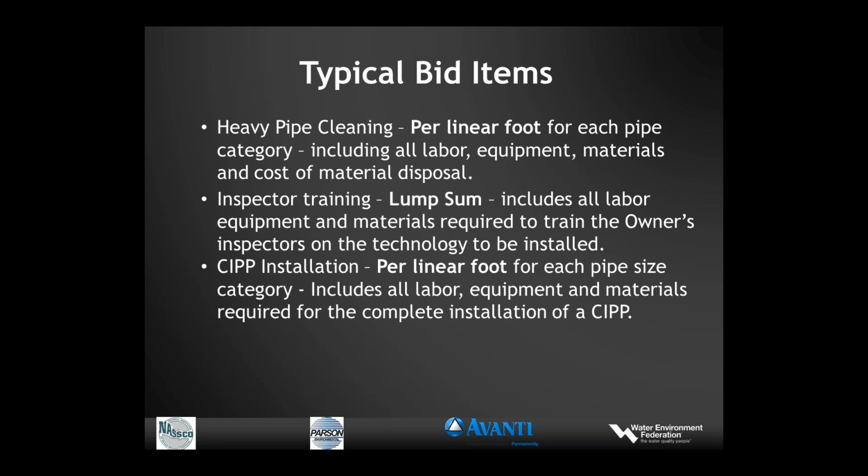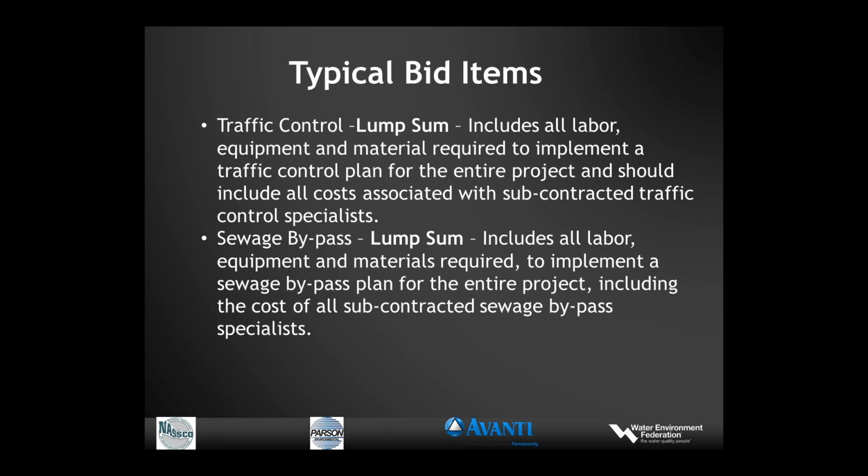Pipe cleaning and heavy pipe cleaning, inspector training. May want to include a bid item to train the inspectors for the CIPP inspection on this project. NASSCO does offer the inspectors training certification program. CIPP installation, traffic control, and sewage bypass.